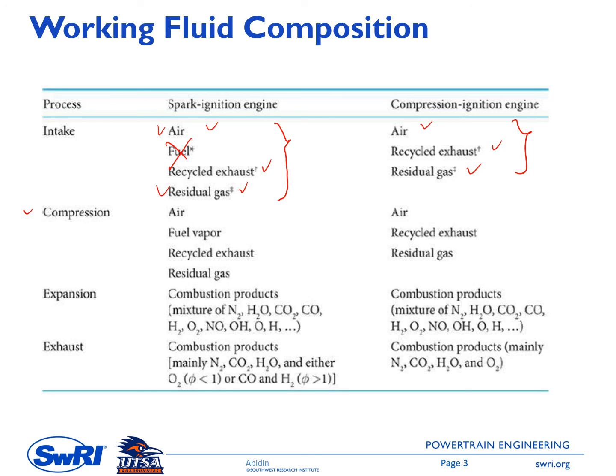During the compression stroke, in the spark ignition engine we have air and we have fuel vapor. Once again, depending on when the fuel is introduced into the engine, we might still have some liquid if it is GDI, or we might already have close to 100% fuel vapor if it is PFI.